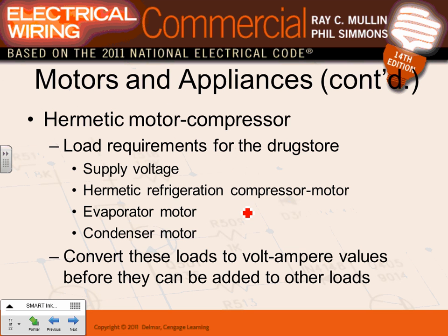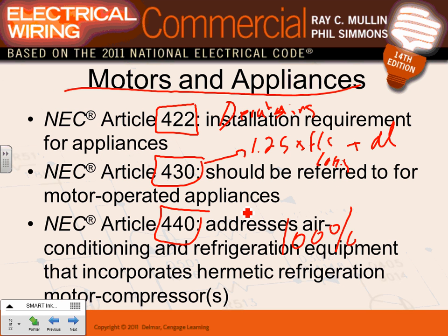General lighting load, we have general lighting load at square foot, 3 times 3.5, and then we have a second one that's half. Is that the unknown? These are the unknown. Is it 3.5 or 3 for volt amp? Is it 3 for residential? We don't want residential. Was it commercial? Was it 3.5? Okay, thank you. 3.5 for commercial.